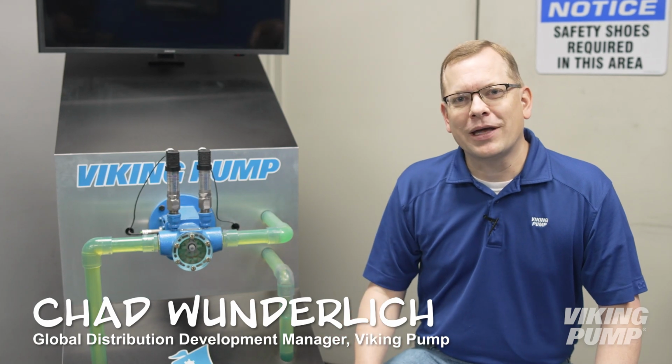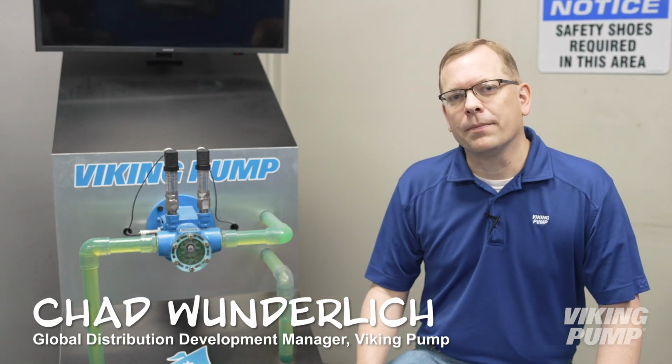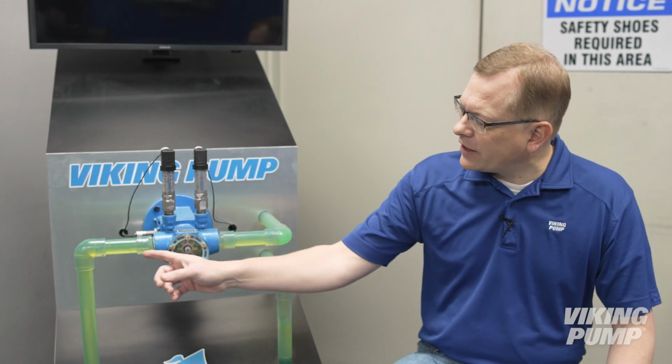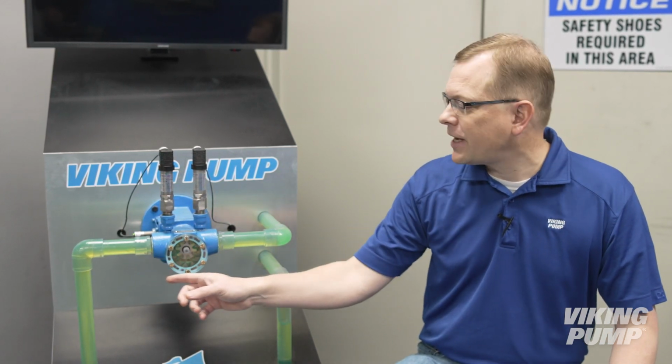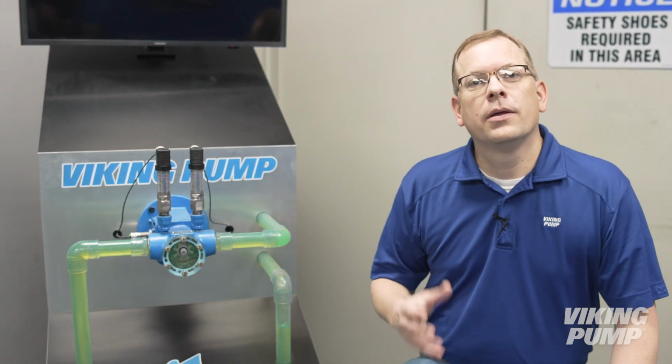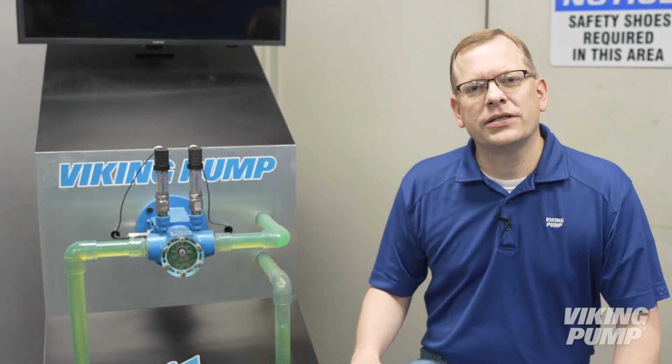Hi, I'm Chad Wunderlich with Viking Pump, and this is an internal gear pump, a type of rotary positive displacement pump. With each rotation of the shaft and gears, a set volume of liquid is moved from the supply tank to the downstream piping. When paired with an AC induction motor, the speed and in turn the flow is held consistent. But what if I need to change that flow?